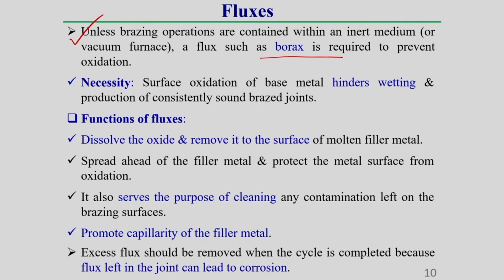What I have already told you, the main purpose of flux is to prevent the oxidation of filler as well as base material. Why is this flux required? First, it prevents oxidation, it also increases the consistency, and it helps to produce a consistently sound braze joint.